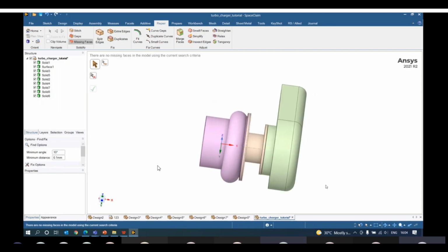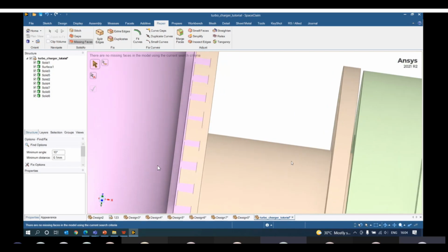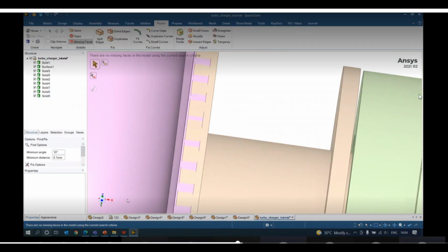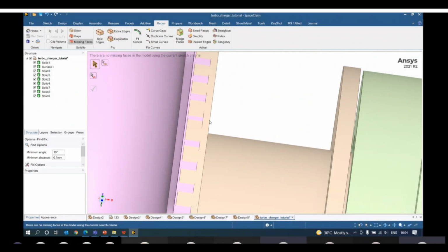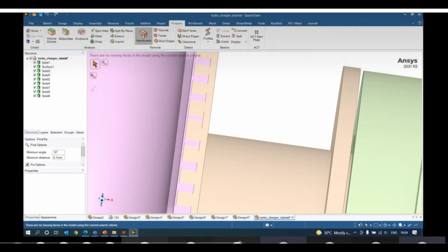So what could be the other issues? We have to find it out. Now look at this geometry. If you look at it, you are able to see that there is some kind of misalignment between the components, right? Whenever you import some geometry here, you will have a single component with a single color. So there is some difference in the appearance itself, you can say there is something wrong. To rectify this kind of issue, you need to use your interference tool.